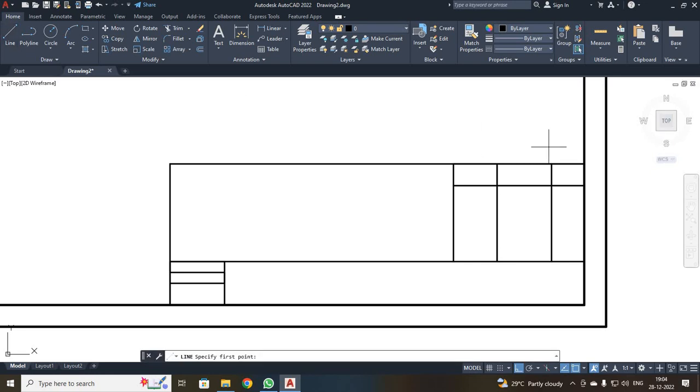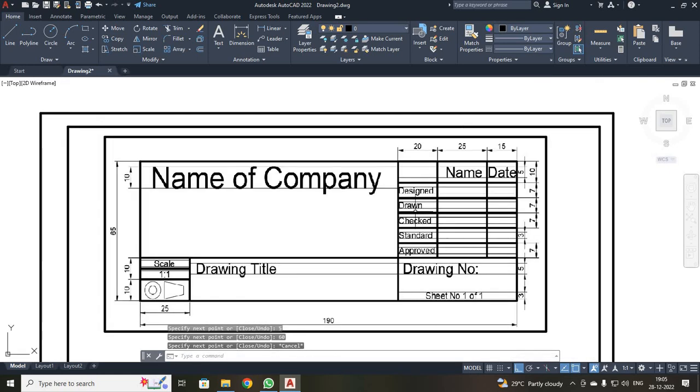First, on your 10 mm I have a point over here. You enter 2.5, enter, move to your x direction 60, enter, move to your y direction 5, enter, and once again 60, enter. I have just joined your first box. I have completed this box.